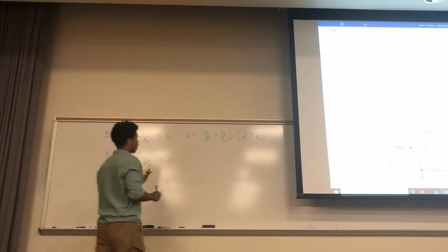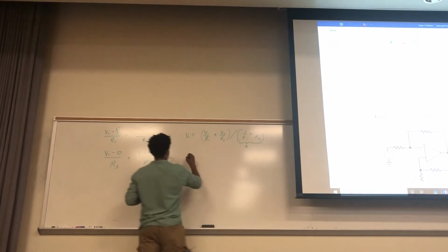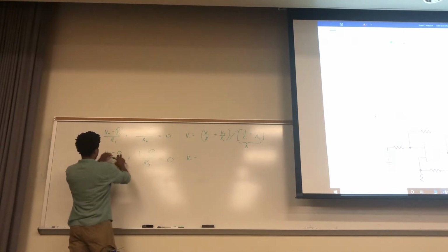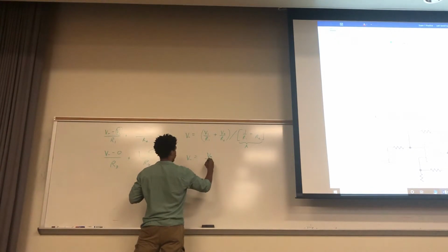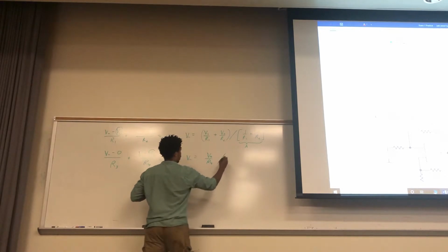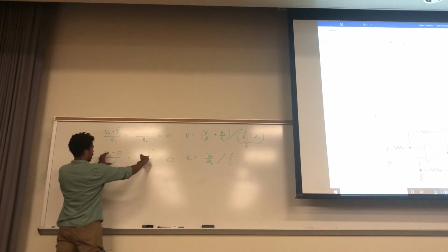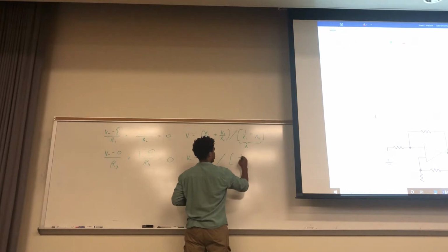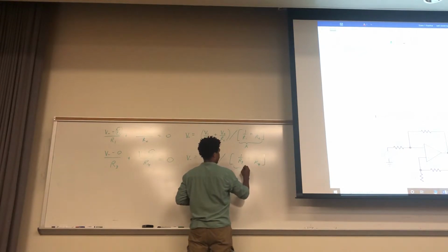Yeah, and so we don't have to carry these around. Let's just call this A. For the other one, it's very similar. But this one is 0, so only that one goes over there. So, V out over R4 divided by, we factor out the V minus, and so we have the 1 over R3, 1 over R4 is just going to come down here on this side. Okay, that's 4, and we'll call this B.